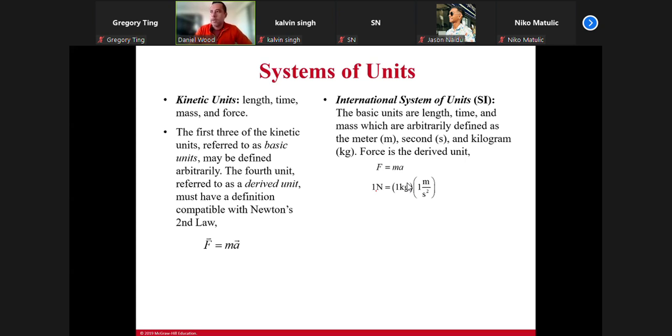Okay, but it must be compatible. You can't go and say, you know, mass divided by area is newtons, right? Mass divided by area is pressure. It's not newtons, it's pascals, right? If the units are in kilograms and millimeters, it's going to be megapascals, right? So you've got to be consistent with your units. This is one thing I've noticed in teaching MM211 in first semester, is you guys really need to get a hold and really be confident with your units.